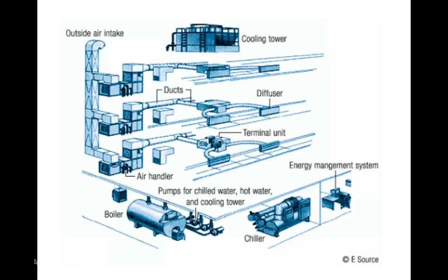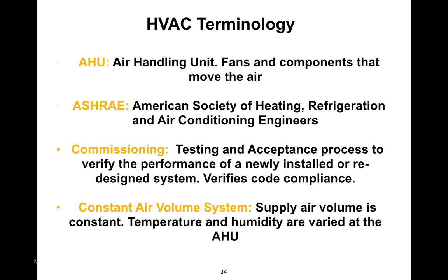Okay, here's another building system. You'll notice that in the basement, they have chillers making chilled water, and that chilled water is pumped to air handlers throughout the building to cool air. There's also a boiler there to send hot water up to other coils in air handlers throughout the building on each floor. So you can heat the air or cool the air as you need it and send it to these diffusers throughout the building. At the very top of the building is a cooling tower, and we're going to talk about cooling towers later on, when we get into the issues of air quality and so forth associated with them, specifically Legionnaires' disease and other microbial issues.